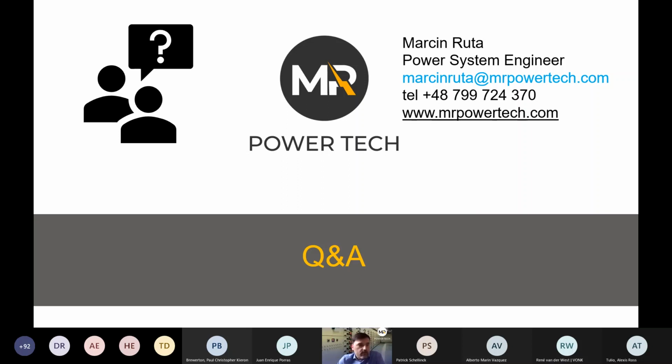As far as I know, it's not forbidden, because IEEE tests are not really related to this. I think the bigger question will be whether you have 50 or 60 hertz. That would be a more valid question. But in our practice, it's no big issue. Follow IEC 60909, because then your protection and your results are more in line with what's happening.